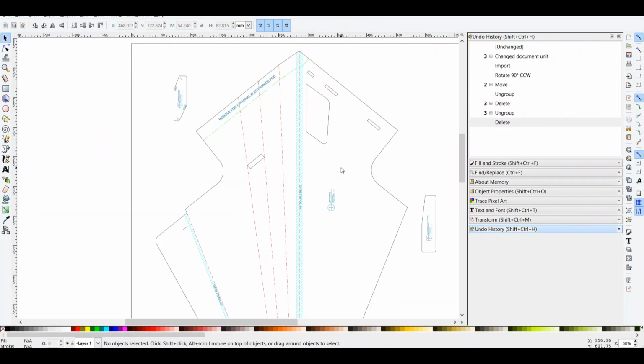Okay, now let's start cleaning up the PDF plan. The end result that we want is that all these parts will be left with just black line, which is for full cut, and then this red line. As you can see, these are dotted red lines. We want to make it a straight red line, so we have to redraw that. Otherwise, when your machine is cutting, it just keeps going up and down on the z-axis. That will waste some time, which you don't want.